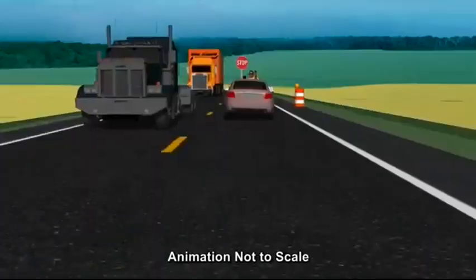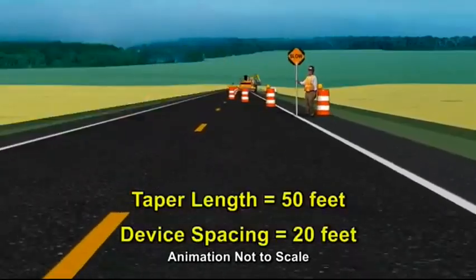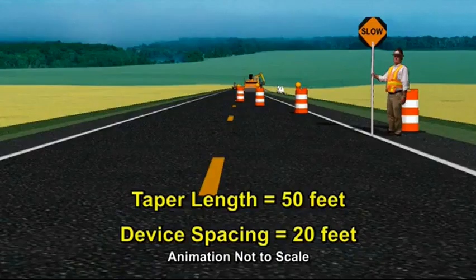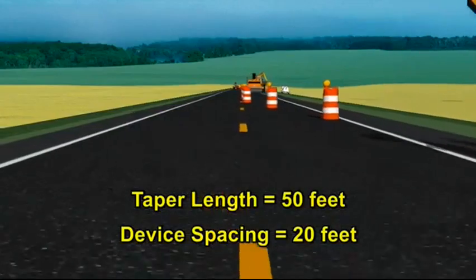The length of the taper is fixed at 50 feet as shown on Index 603. Channelizing devices are spaced a maximum of 20 feet to provide clear delineation of the taper.